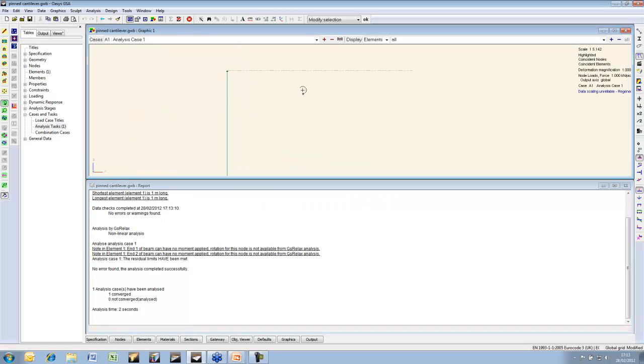And we can see, as you expect, this pin cantilever has rotated until it is in equilibrium with the load, i.e. it's hanging straight down. So with the GSA non-linear analysis, you can deal with some actual mechanisms, as long as there is a sort of final resting point in place. Yeah, so some way that the structure can finally balance the loads.